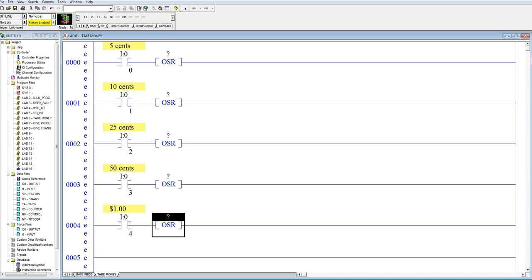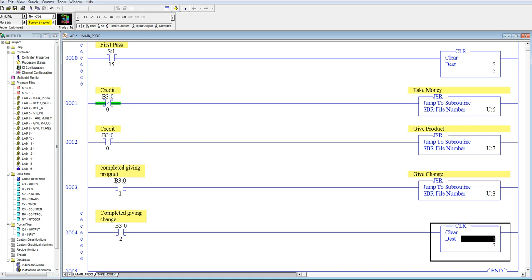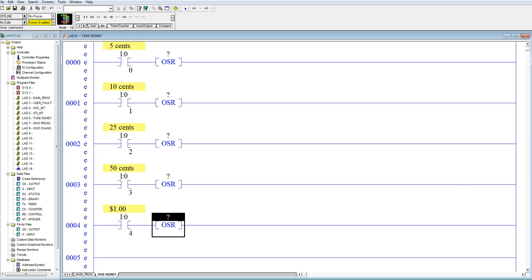All right. Well, anyway. So I've got. Now the issue is: did we or did we not use binary bits in the first instruction? And the answer is yes. So B0, 1, and 2 are already used. So the next binary bit is B3. B3:0/3.